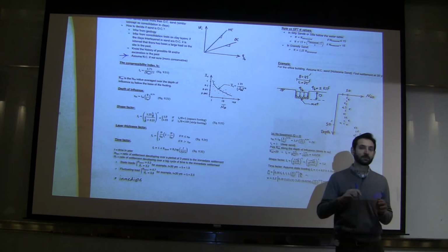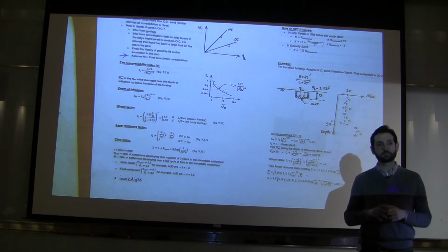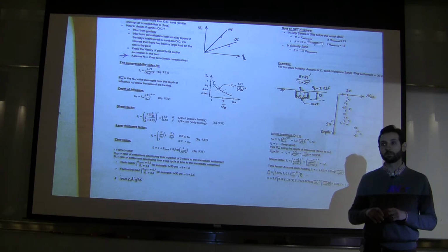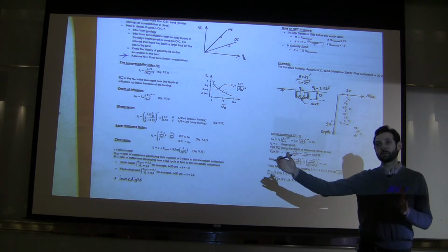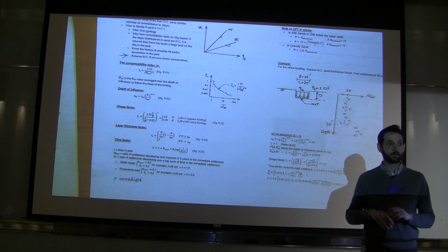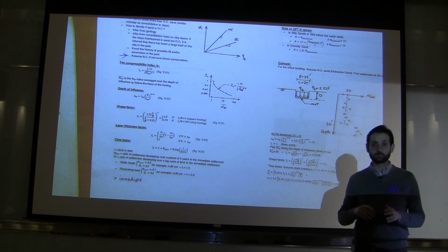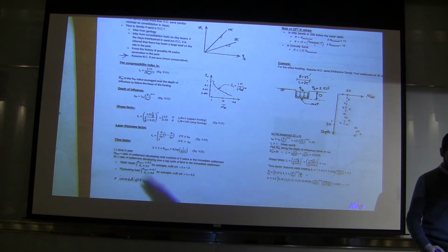So what that means is that you have a new building, you build it, you get 2 inches of settlement right after all the load is on the building, and then over time, after 30 years, you get another extra 1 inch of settlement. So total settlement would be 3. This time factor takes care of that.